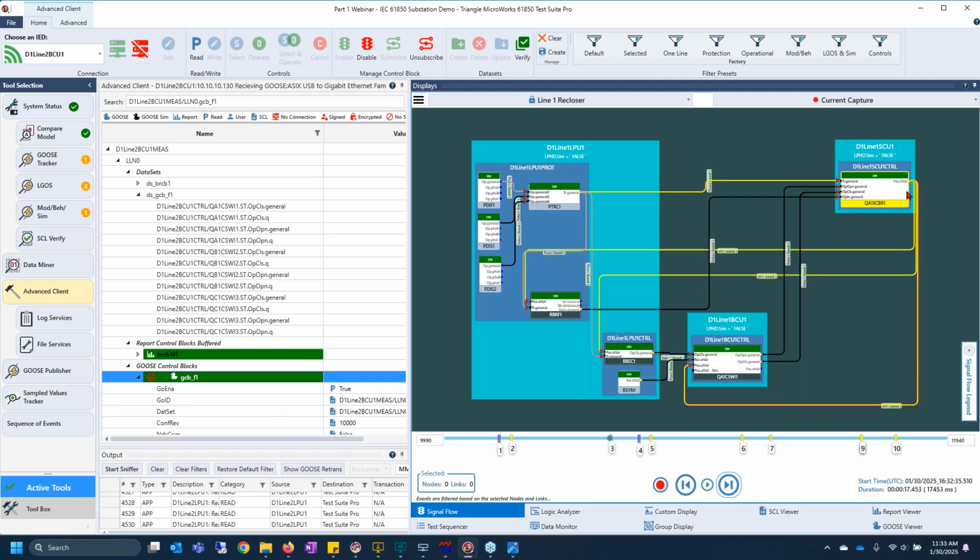When the breaker position changes, it sends out a GOOSE message to several different places, including the CSWI. So Jackson mentioned that earlier. That's the controllable switch. This is the BCU controllable switch. So that is the bay controller unit. It also let the recloser know, hey, the breaker's open. So if you need to do your reclosing thing, do it. You can continue to step through.